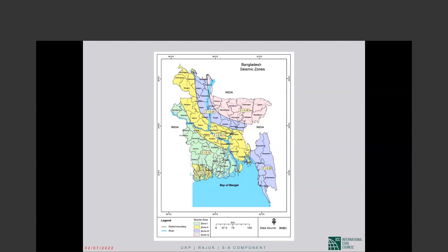And when the infill is lost, the stiffness of the building drops pretty drastically. Obviously, not all the infill is lost at one time, but even then, in a significant earthquake, the stiffness will go down significantly, and then the building has a different period. It is in a different range of earthquake.